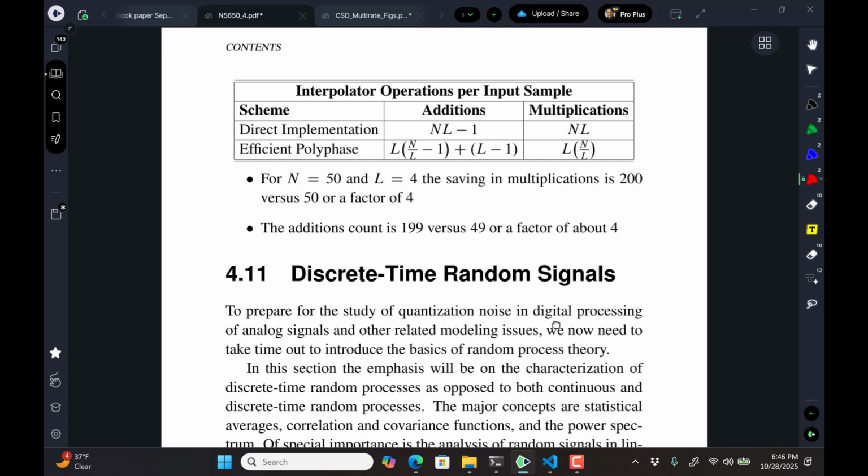So we came up with a very simple moving average filter, a cascade of moving average filters that had very low complexity, and that was able to shape the spectrum enough to meet the emissions requirement. So that was not a polyphase. That was just the FPGA people implemented directly, and I modeled it all in Python and verified that it met